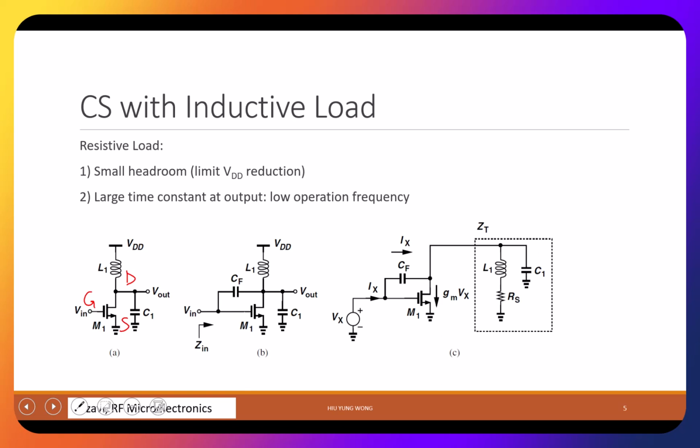I hope that you won't feel surprised, because we are talking about high frequency, right? You almost don't have resistance in the inductor. So if you're talking about DC, no way, then you have some problem. You don't have gain because there's almost zero resistance in the inductor. But now we are talking about AC. So in this AC case, you actually can have a big gain, right?